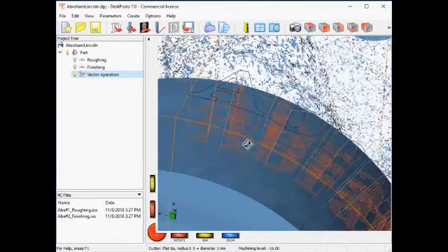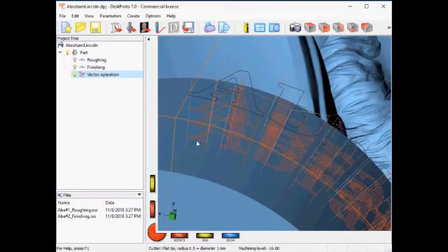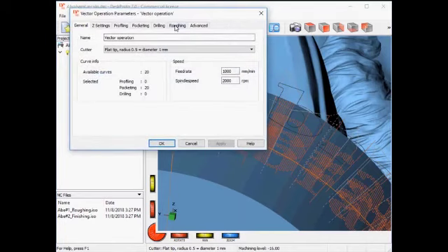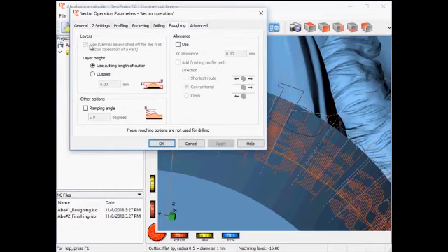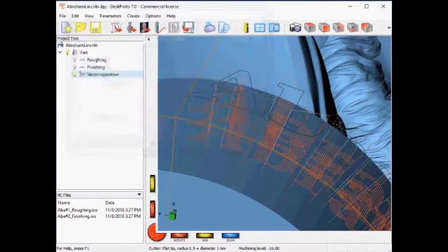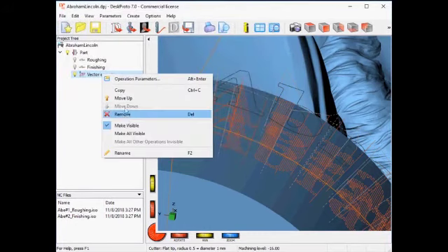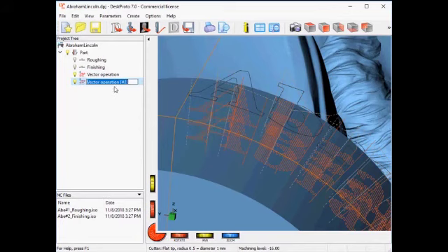And now I can see that layers are used, roughing layers, which is obviously not needed here as all material has been removed already. However, I can't switch them off as this is the first vector operation of this part. So what I do is use a trick. I copy this vector operation, I call that one text, and this one will be called dummy, as this is an operation that we will not use.